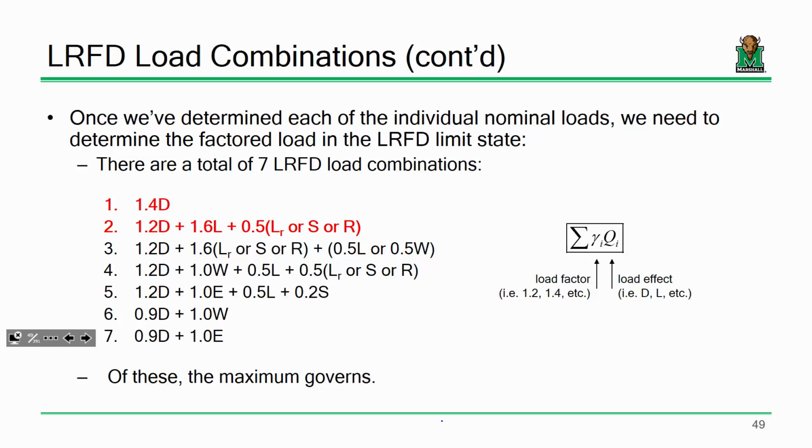That's important stuff. That load combo, 1.2 times the dead plus 1.6 times the live, is something we will use throughout the semester. Guaranteed. Yes, sir? What do W and LR stand for? Okay, W is the wind. LR stands for live roof load, and live roof load is basically workers and people like that on the roof.